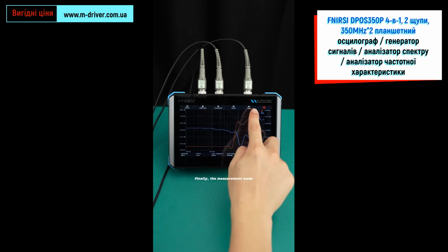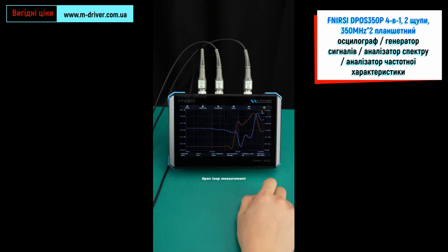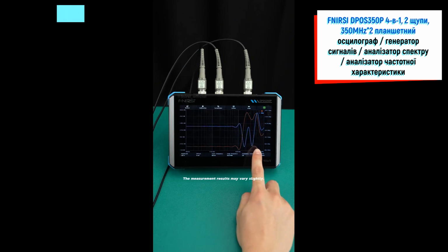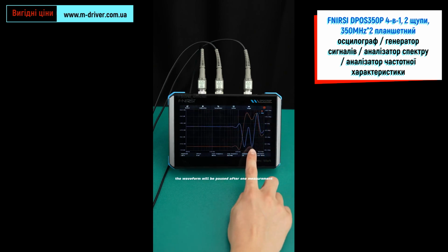Finally, the measurement mode. Next to the pause, this is the measurement mode. Single measurement and cyclic measurement can be selected. In cyclic measurement, you can see that this waveform will keep changing. The measurement results may vary slightly. In single measurement, the waveform will be paused after one measurement. You can see that the current waveform has been paused.